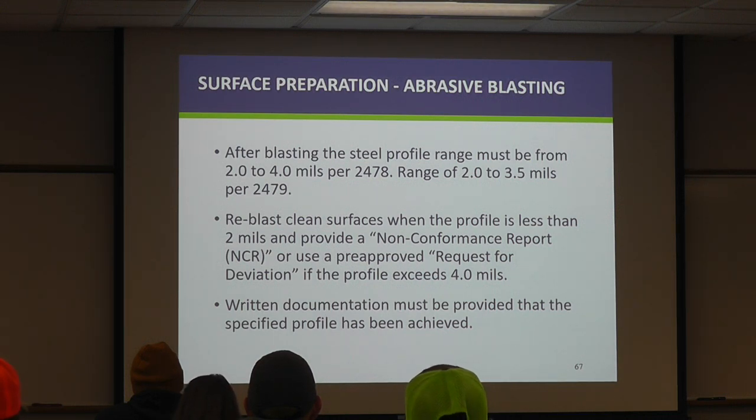So if you were to magnify that on a cross section, you've got little peaks and valleys as to what you feel. So you don't want the depth of that to be much more than 4 if at all possible, or they might really be ripping into the steel. If it's the second time it's getting repainted in the field, it could very easily get up into that range.